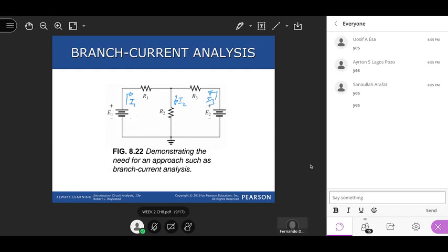After we do that, we assign a voltage drop across this resistor. In this case, this is plus, minus, and plus, minus, because always the current goes into the higher potential, and we explained why already. So this is going to be called V1, this will be V2, and this will be V3, right?